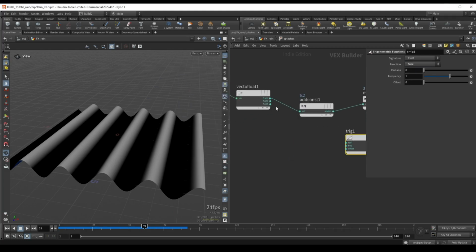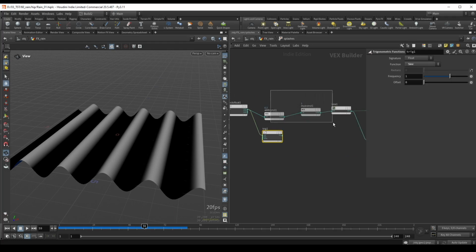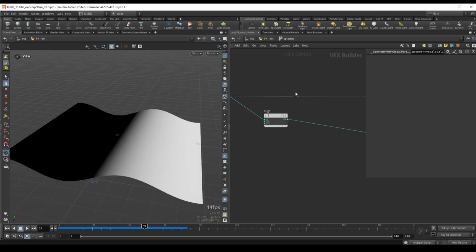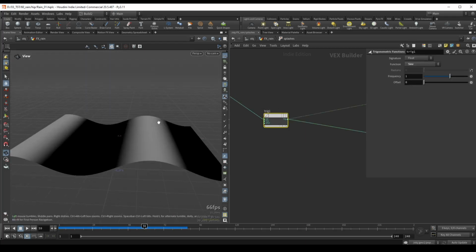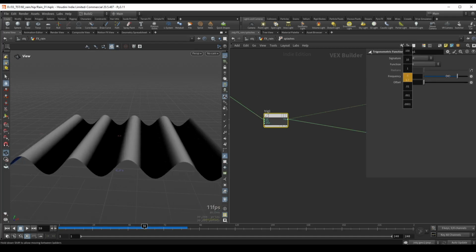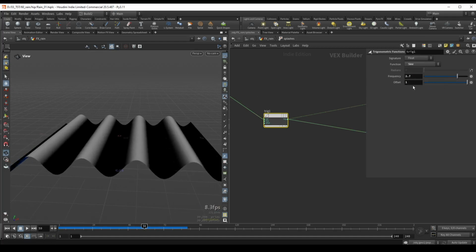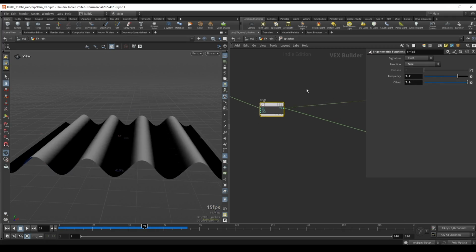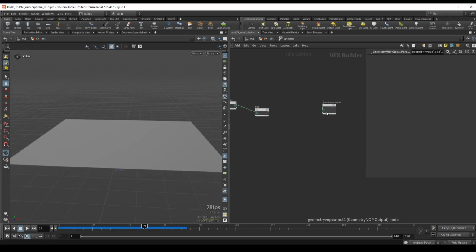So we'll just use the sine function here, and we can plug this back inside our radius, and I can remove our 3 nodes over here and just use this one instead. And if I reconnect our values here, and connect this here as well, now I have the option to control the frequency and also the offset. So the same thing we had earlier, but this is just a little bit cleaner.